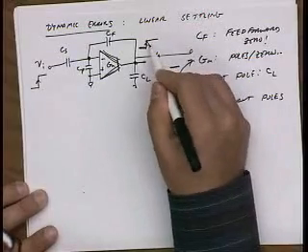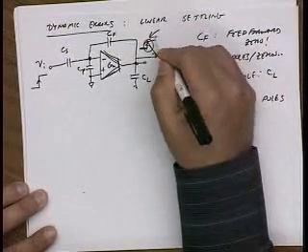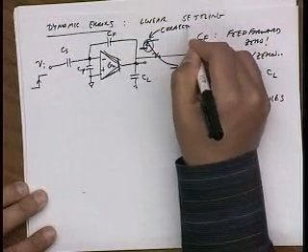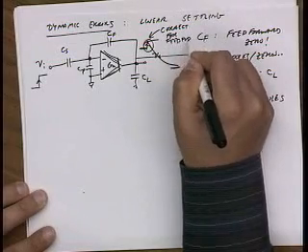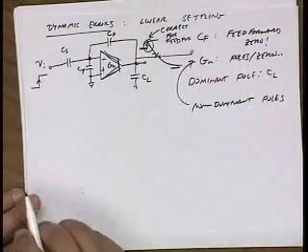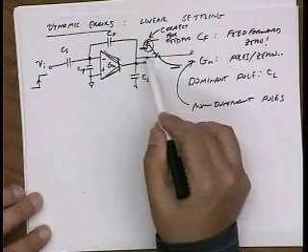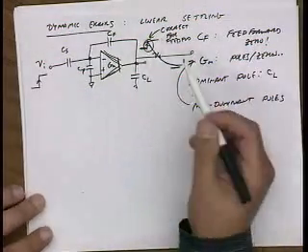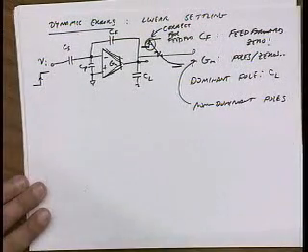So the first thing the amplifier does is it actually corrects for the feed forward. And then it settles to the final value. So this effect of the 0 apparently may be important. It's something we should try to take into account when we do our analysis.